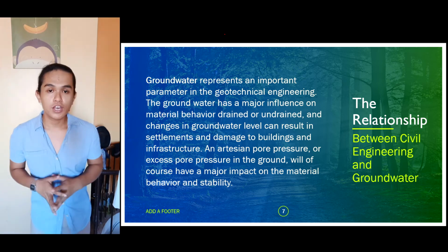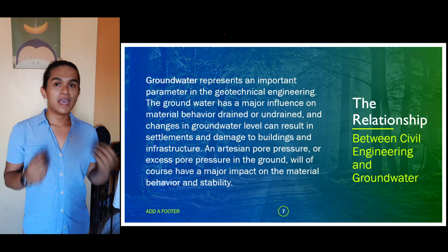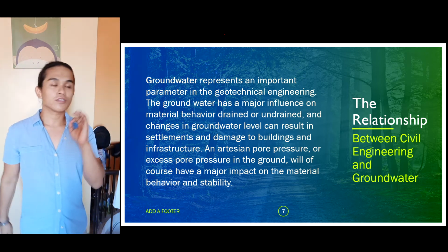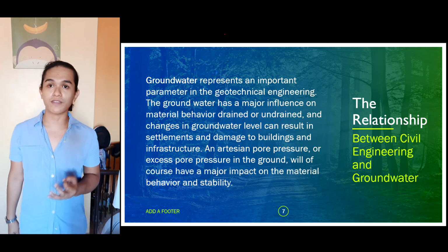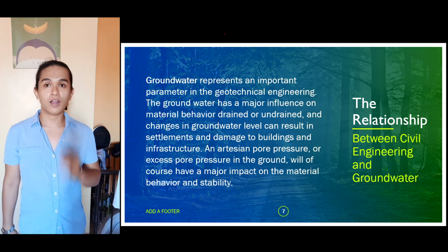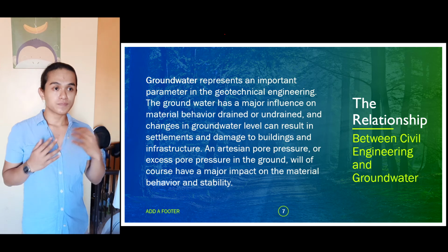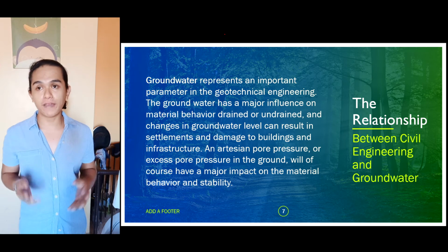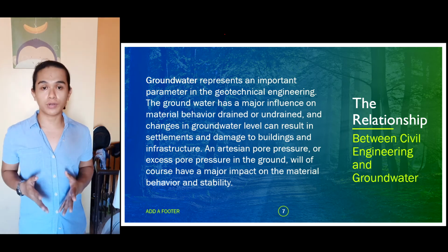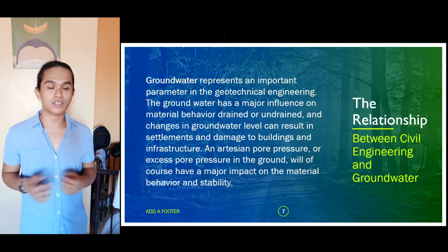and stability. So considering water present in our construction site, we have to be careful in digging, because most of our works involve excavation, and this excavation could reach our groundwater or water table that could possibly put excess water on our construction site that would be harmful or damaging for the soil, and that would affect its stability in holding structural loads, and that is very crucial in building a structure.